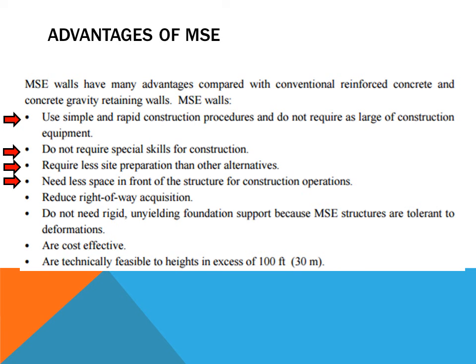Then they need less space in front of the structure for construction operation, and they can reduce the right of way acquisitions. They do not need a rigid unyielding foundation support because MSE structures are tolerant to deformations. Of course, they are cost effective and technically feasible to heights in excess of 100 feet.